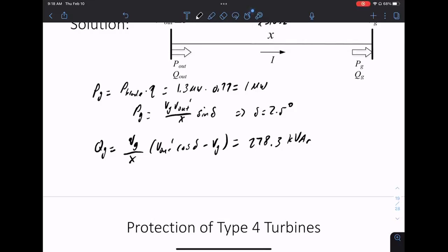Oh, so your generator is not perfect. Your synchronous generator is not perfect. Yeah, there's some efficiency there. So you have some blade, and that gearbox. Yeah, you have that. That doesn't need to be perfect. 77% is a little bit low; nowadays the efficiency is much higher. But there is always some loss from the power capture blade to the high voltage end of the transformer.